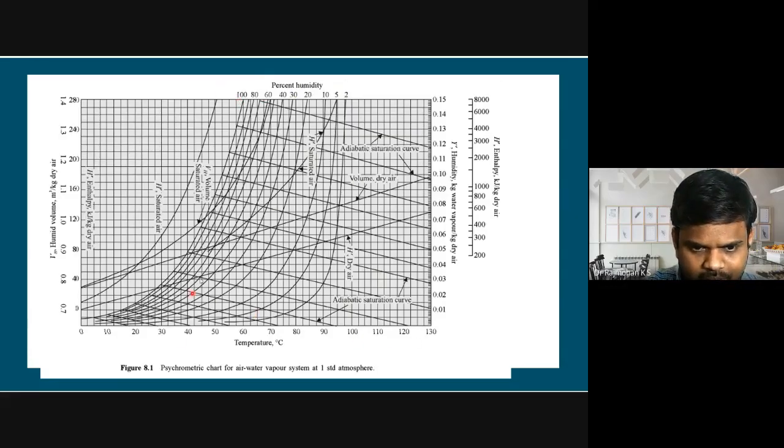At the same temperature, we will have wet bulb temperature also. These slanting lines are the wet bulb temperature lines. And we have the enthalpy data scale also. Different graph sheets have the data scales given at different places. However, we should be careful in seeing what unit is mentioned here. We have to use the appropriate units, and convert to required units also.